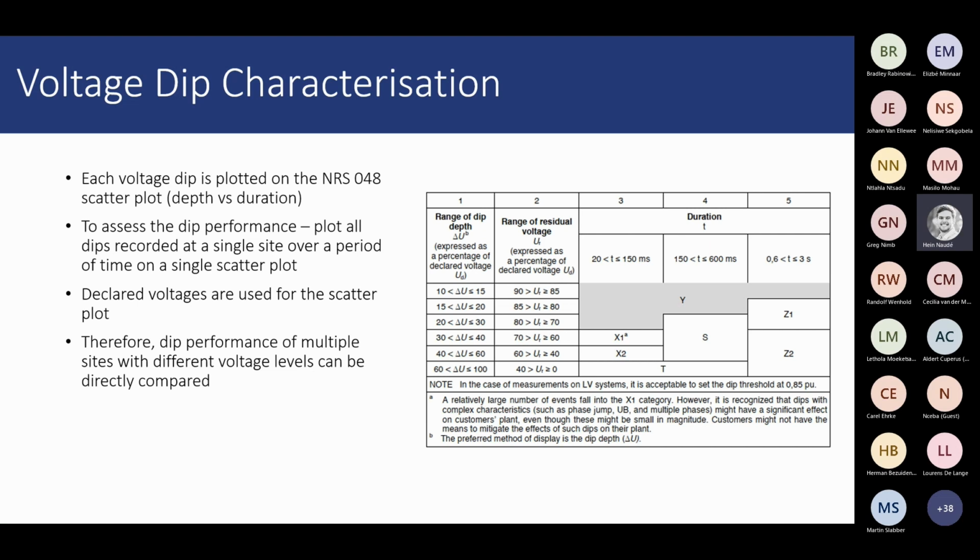And that's where we, at the moment, want to introduce, or mention, low power VTs or voltage sensors, whatever you want to call it, because the way that it functions is like a resistive divider. So there's no non-linearity in higher frequencies. You get a more accurate representation up to very high frequencies, broadband. So it's a broadband VT with high bandwidth. When you want to investigate harmonic emissions specifically, even not that high, at 1.5 kilohertz and up, it becomes important to consider what VTs and CTs are being used that you're measuring on, because that will have an impact.